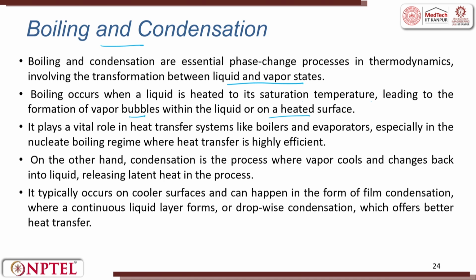That is why when you heat a pan in which you have put water or milk from the bottom, you will see vapor bubbles forming on the top. So, the liquid is heated to its saturation temperature, leading to the formation of vapor bubbles within the liquid or on a heated surface. It plays a vital role in heat transfer systems like boilers and evaporators, especially in the nucleate boiling regime, where heat transfer is highly efficient. So, you should understand this point.